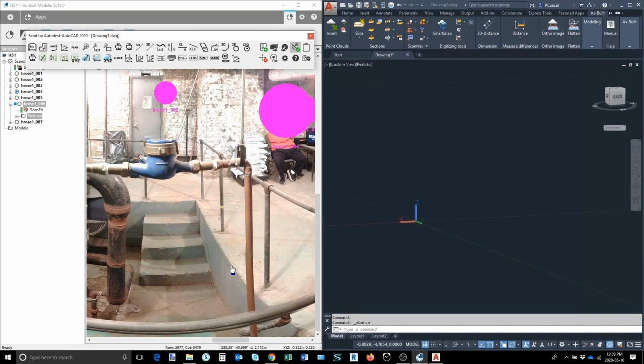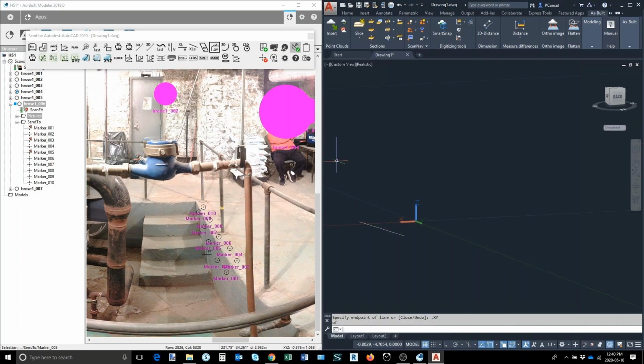You use your image. And so for an example, when it comes to extracting edges, which is a little bit difficult if you are dealing with a point cloud, we can use this macro that extracts edges by making 2 clicks, one on the face and one on the top. It will pick the X and Y from the wall and the Z value from the top. So by 2 clicks, you see that I can extract the edge with extreme accuracy here. Even if the edge is a little bit noisy, I can extract it very nicely. I can combine this command with an extrusion command.